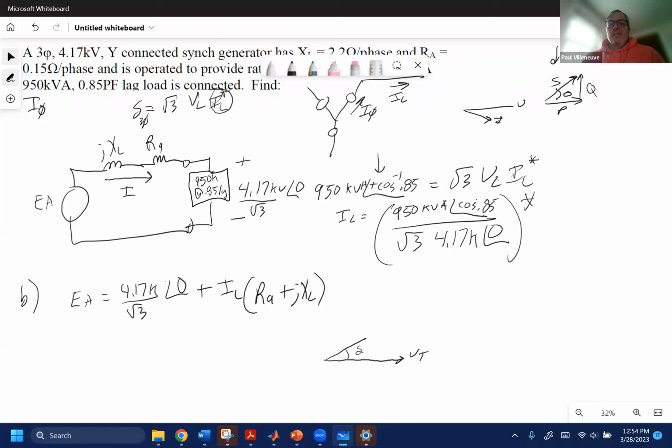So it's out of the machine. If P and Q are both positive, we have the positive angle because of the power out. And the Q means it's an overexcited machine, providing more reactive power than what's needed. So if you recall from our phasor diagrams, the magnitude of EA is going to be greater than the magnitude of VT. Another way to check that is to look at the magnitudes of the voltages and see if I get reasonable results.